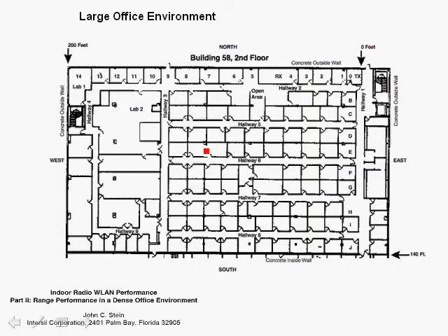Here's a large office environment in which many factors come into play. The multipath channel that you encounter depends on where you are in the office environment. For example, in a laboratory environment, you will have cases where there are no obstructions, so you have multiple reflections off the wall, and the delays are actually larger than in a cubicle environment. And say you had an AP in this location here, then you would have multiple reflections within a bounded area, and the delay spread, or the RMS delay spread, which we'll define, would be much smaller than in the case of an open laboratory environment.